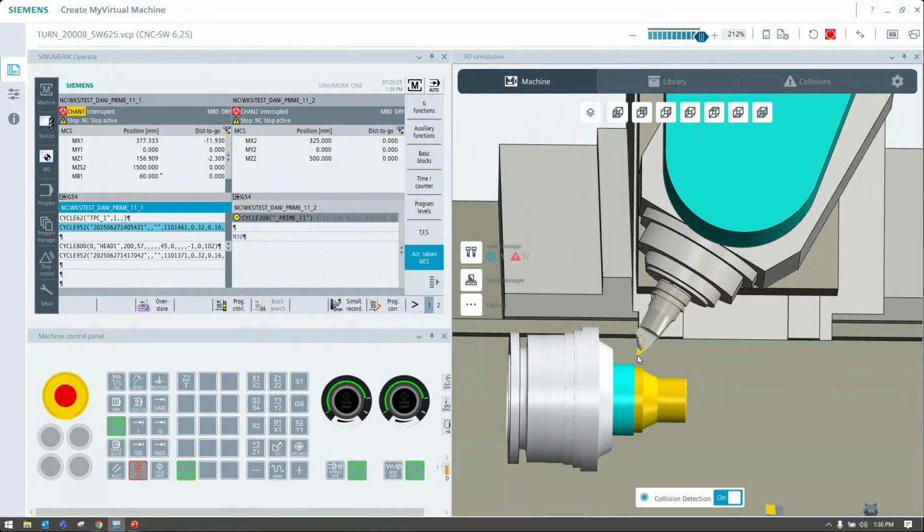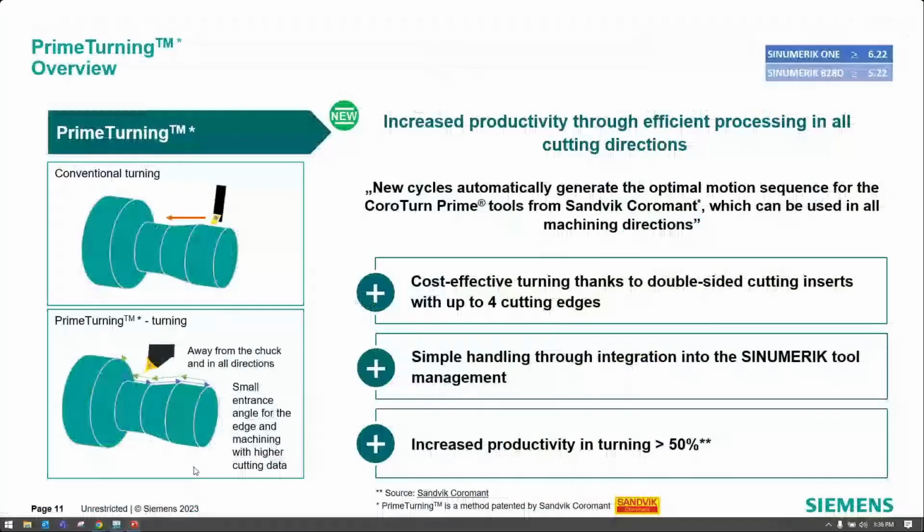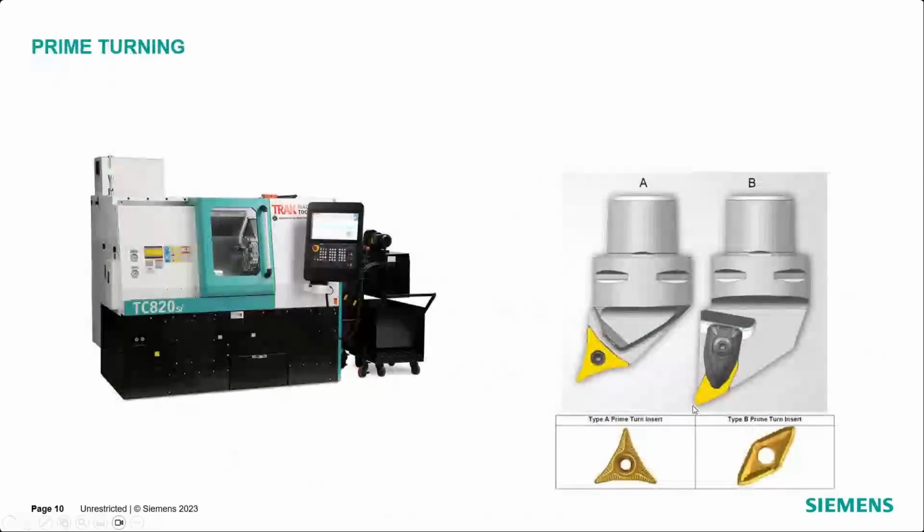It must have something to do with the infeed, right? Because when you're back turning, it is going to plunge straight in to chip depth. So I guess for whatever reason, that insert will not plunge like a traditional ISO style insert geometry. And I'm assuming probably because you have two contact points, because if you're coming in there, you're plunging straight down. As you're arcing in, you're getting more of the material. I'm not quite sure of the reason why, but I will say firsthand knowledge, yeah.